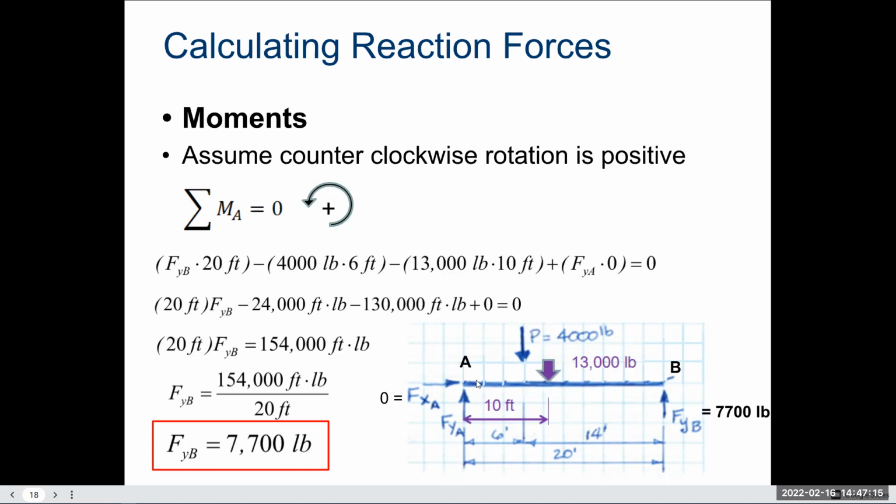Finally, force A, we're actually comparing it to where the hinge is. Remember, we can't rotate at the hinge itself. And so that's why there's 0 distance from the hinge, hence 0 moment or 0 torque.